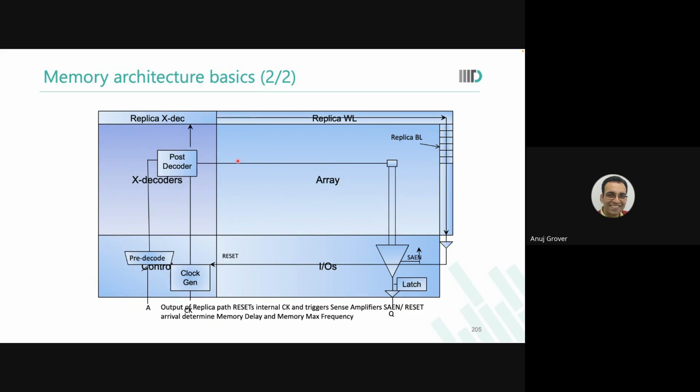Now consider a memory cell over here. Now this memory cell was selected much earlier than the replica word line was selected. And this memory cell or the sense amplifier in this location will get triggered much after this one, which is on the corner. Are you able to see this? So this particular memory cell will generate much more differential than the one in the corner. So what we have essentially ensured through this mechanism is that my cornermost sense amplifier is the worst sense amplifier.